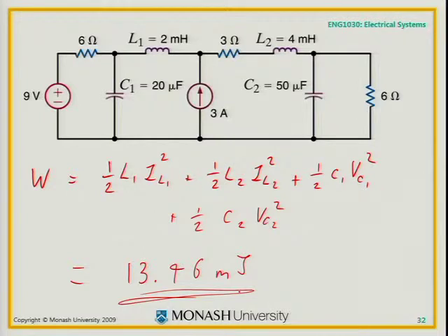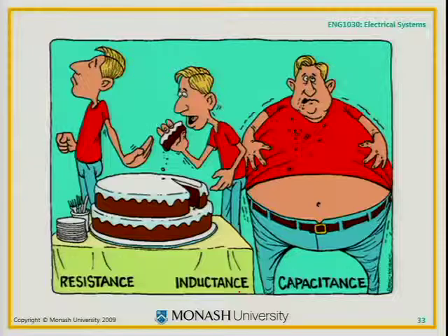Who thinks parallel to be bigger? That's the opposite of resistors. But it shouldn't be counterintuitive. If I've got a whole lot of capacitors in parallel, I can have a certain voltage. Every one of them can hold charge. So I keep putting more and more in parallel and I'm holding more and more charge. So the equivalent capacitance must be getting bigger, not smaller like resistors. Indeed, that's the case. So, there's resistance, inductance, and capacitance. You'll never forget them.